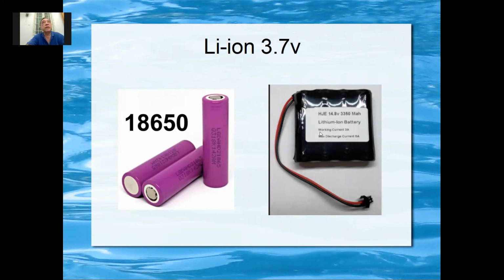Sometimes they put these lithium ion batteries, they pack them up, 4 pieces, 8 pieces, whatever pieces, and just solder them together. But what you cannot see here is actually an electronic load balancer. Without this load balancer, you cannot charge the battery. The battery will overcharge, because if you put them in series, then you have a problem.